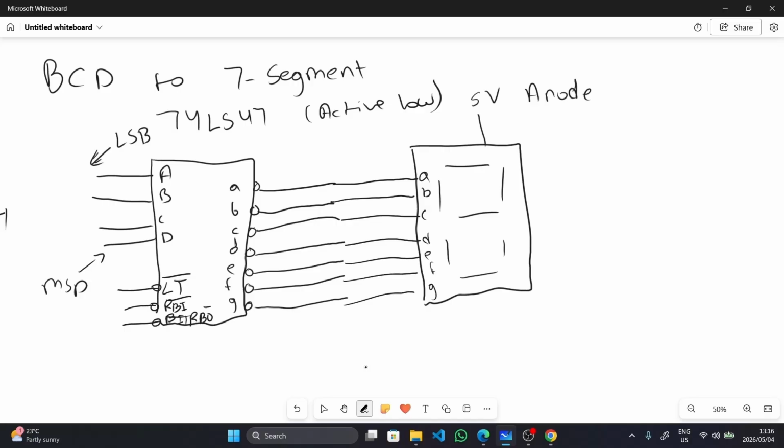And in this case, just remember, it's active low, right? So which line should be 0 and which line should be high. And just remember, we are supplying 5 volts. So it's something like this. So it's a current sinking. So let's just say it's the same as this.